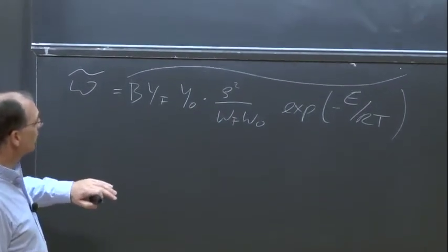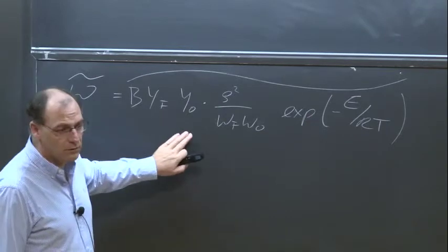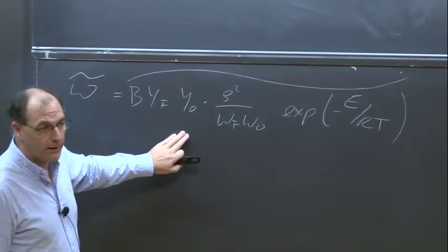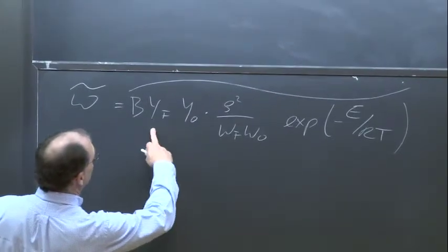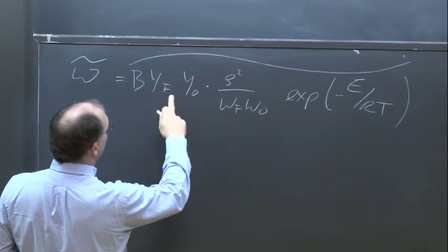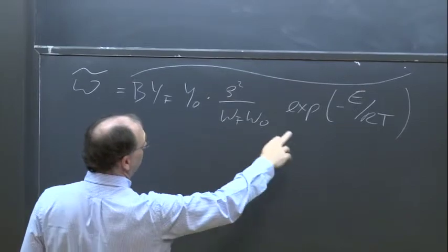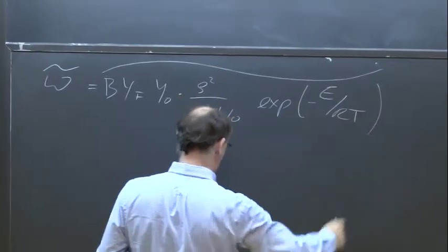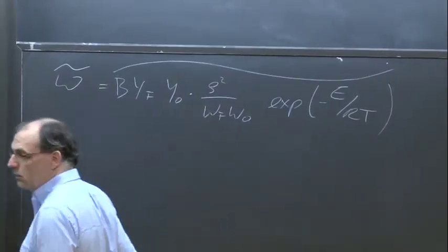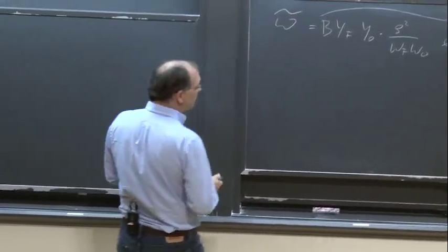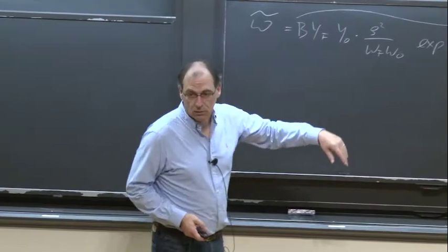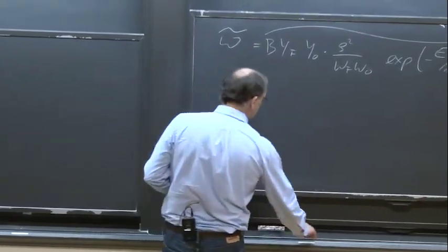And then we would have to, like we did before, introduce here the Reynolds decomposition, which would give us something like Y mean plus Y prime, Y mean plus Y prime. Here we have T plus T prime, and so on. And you see, you get an awful lot of correlations. So let's say we want to neglect all these correlations and just evaluate this with a mean.